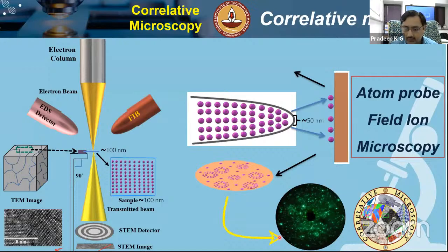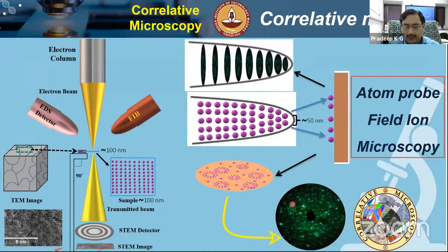This is an image of a nanocrystal where we have multiple different nanocrystals oriented in different directions, surrounded by an amorphous matrix. When you have an amorphous matrix, the atoms are randomly distributed, so you don't get any periodicity here. Whereas these nanocrystals are visualized through the orientation differences from their crystallographic poles. This is the easiest way of looking into the field ion microscope for nanomaterials. But if you have micrometer scale grains, then you will see all of the crystallographic poles nicely visualized, as in the case of a stereographic projection.